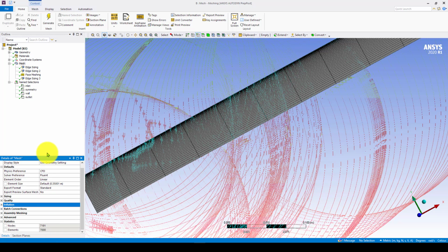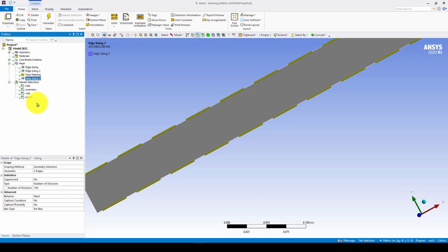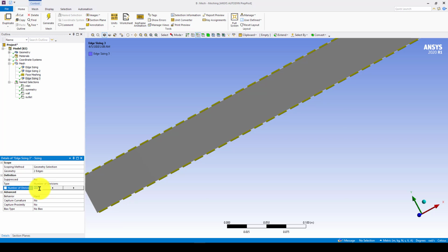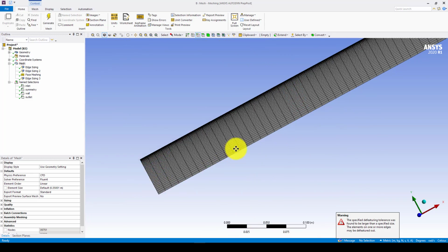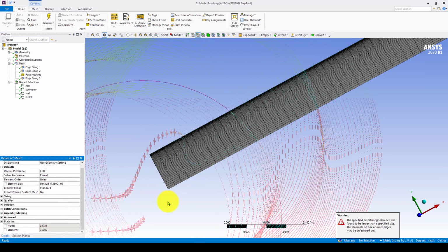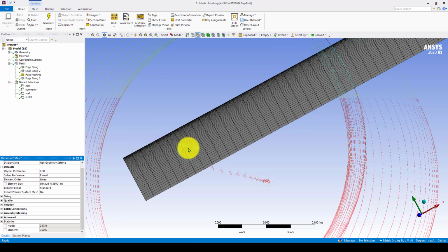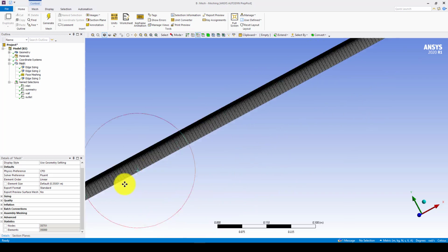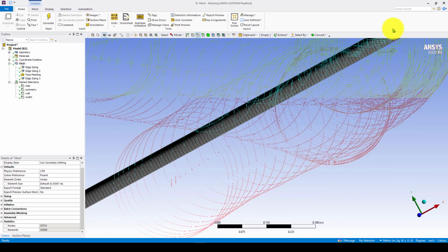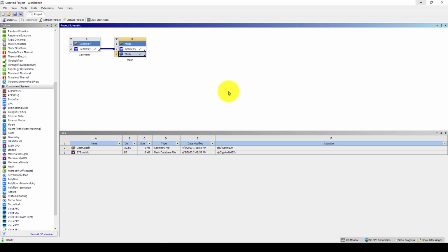So this is a small mesh, but let's say we want a better quality. So let's add more elements here. Let me put 400, 500, or let's say 700 is better, okay? Generate, and see that we have a finer mesh. And here we have 35,000, okay? So you can go larger. Since we're doing 2D, there is no problem getting large meshes. It's relatively fast. So let's take this one for granted, but remember you can get something finer. So we close the mesher.